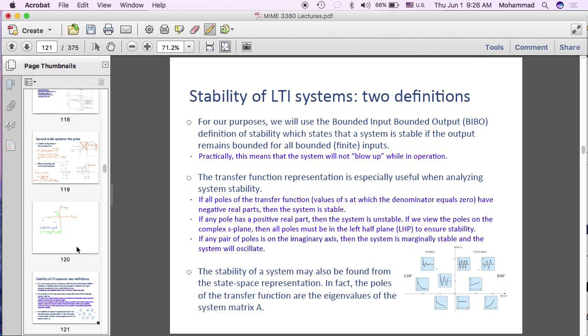Okay, so we talked about the transient response and the fact that location of poles on the complex plane will define the response. By the way, these figures, I have a larger version of it. These are impulse responses. You remember impulse responses? They are effective initial conditions, as if you only have some initial conditions and let the system run. So depending on the location of poles, you have various impulse responses. You can see that as we get closer to the origin, the response gets slower. And if you're exactly on the imaginary axis, the response gets oscillatory.